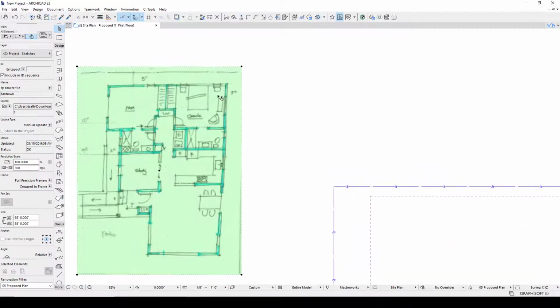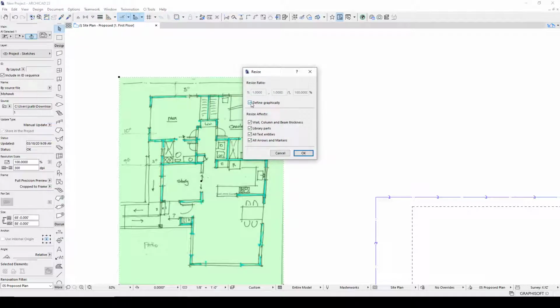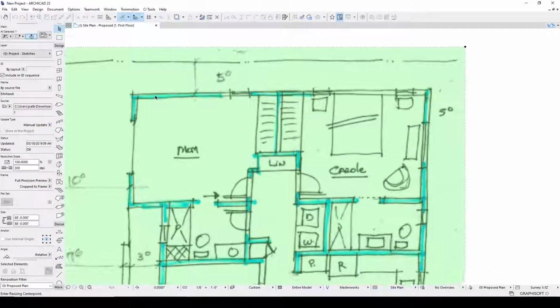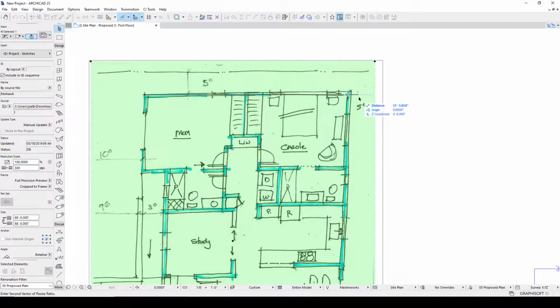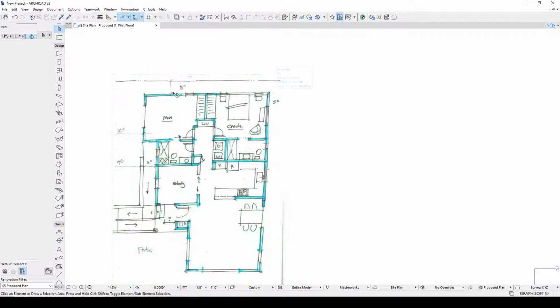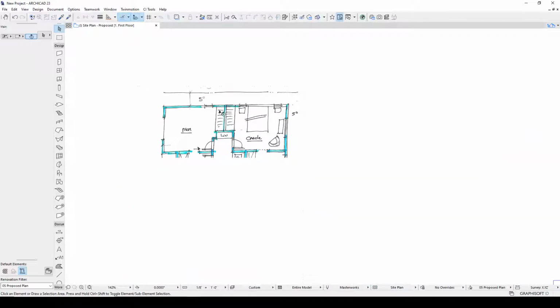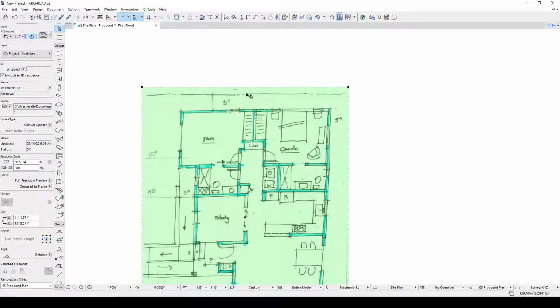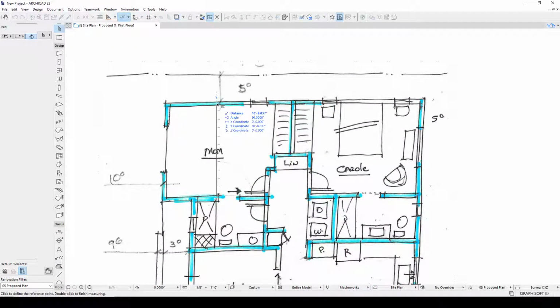So what I do, and I encourage you to do the same, is, well, first we want to resize this. If we select it, hit Control R, define graphically. I happen to know that this wants to be 30 feet. So I click the 2 points and I type in 30 explicitly. And then I'll just check to make sure that these dimensions, no, maybe that wasn't 30. Or that wasn't accurate. So I want to make sure that I've scaled my drawing appropriately.